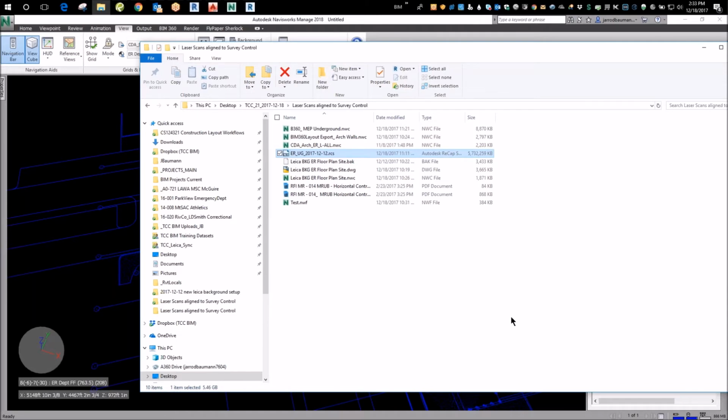And then exporting to a unified scan means it takes all those millions and millions of points, and it looks on every surface and says, oh, you want me to decimate everything out that's closer than 2 millimeters. So it leaves only a dot every 2 millimeters, which is like a 1/16 of an inch. So it's still very dense, but the full project is like 9 gigs. This is a 2 millimeter decimation. You could go to 5. It would still be plenty of data, and it would cut that number way down for portability. But this should be good.